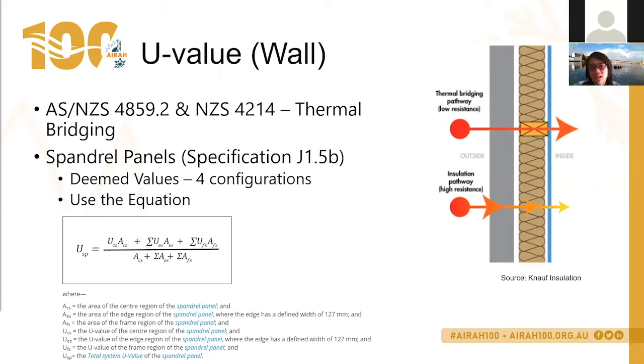What that meant was that a lot of practitioners went, okay, if I put R2.5 insulation between my walls, then my external wall performance is R2.5. What we found is that with thermal bridging, particularly from impacts like framing, where you can see in this image that this stud doesn't have insulation, there's a bridge that allows heat flow to go through. When that happens, it can undermine your insulation R value by more than 40%, purely because of thermal bridging.